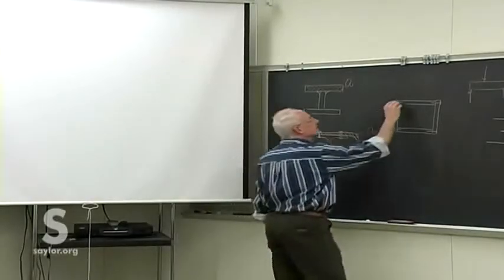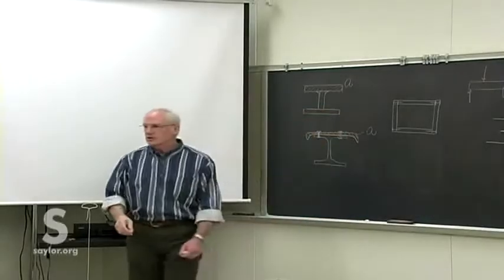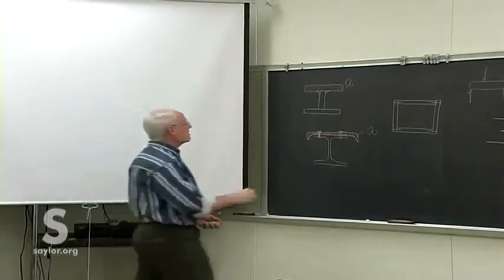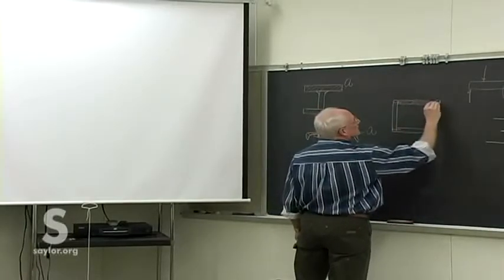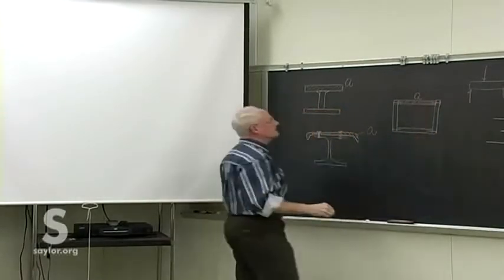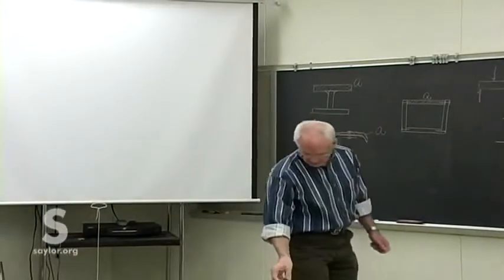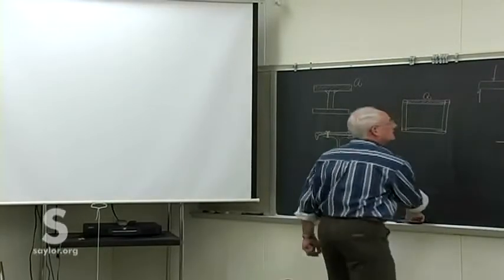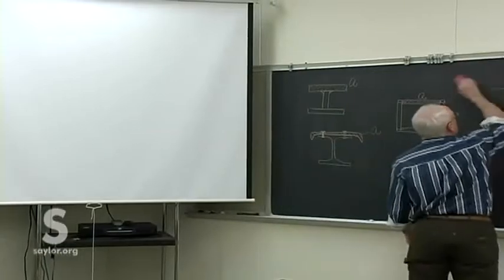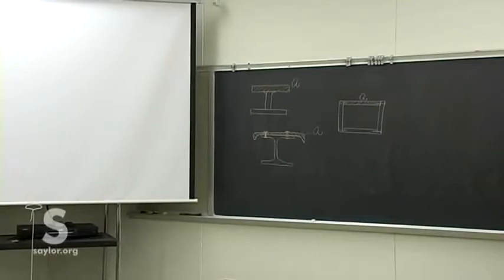So the planes of interest then are these planes here where the longitudinal shear could shear through the nails. So the area we use for that is then the area of that piece in the middle there between those two planes. So sometimes these areas are a little bit difficult to determine, so we're going to avoid overly complex ones and do ones that are a little bit more obvious so we can make sure it works.